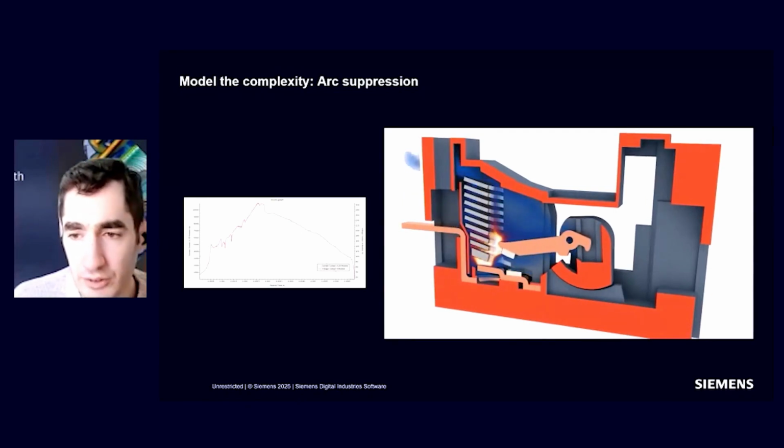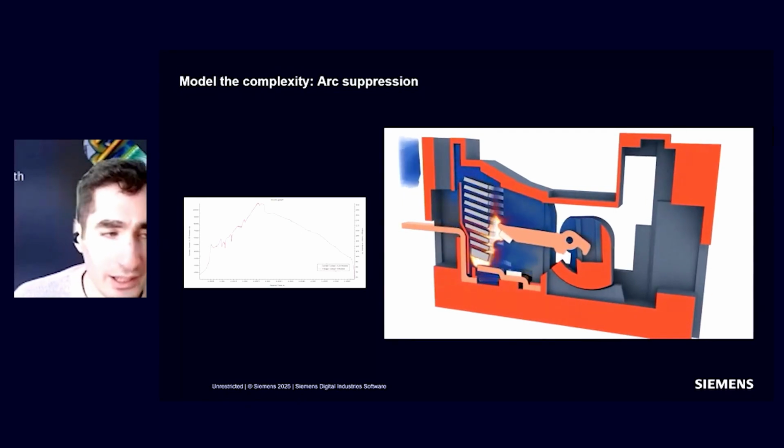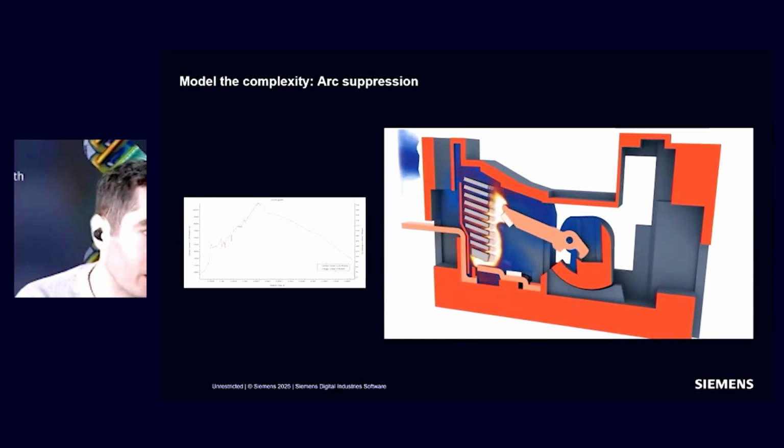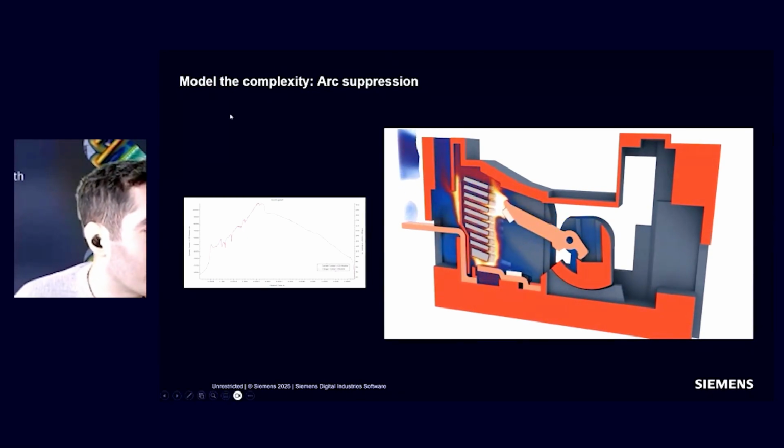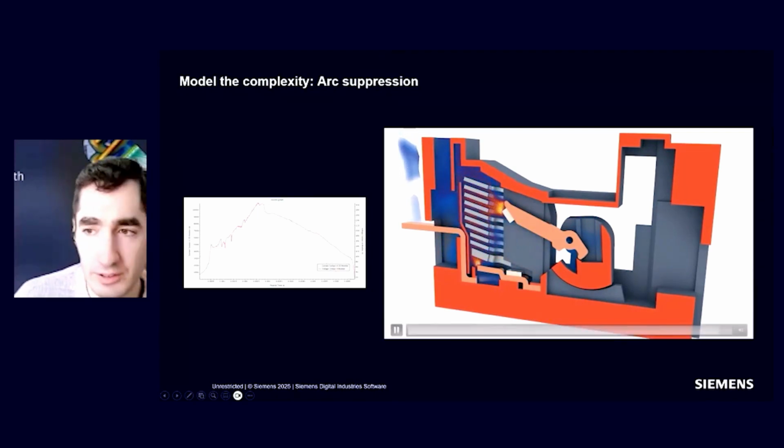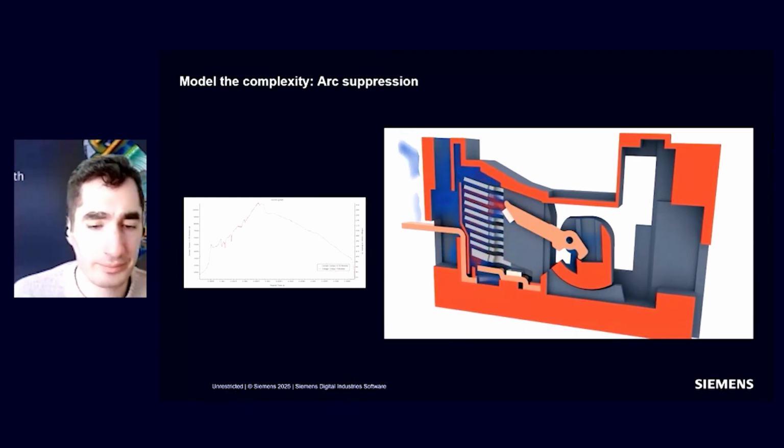And then, of course, also the magnetic and the electric field interaction that is pushing the arc. We can analyze the data, for example, producing plots such as oscillograms, which are key plots to study the behavior in short circuits of our circuit breakers.